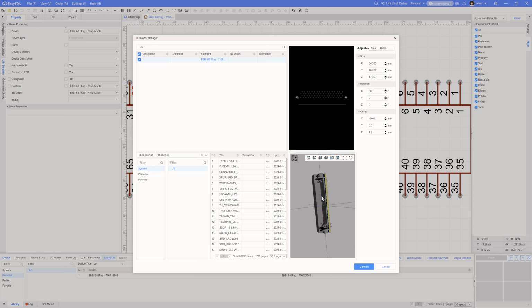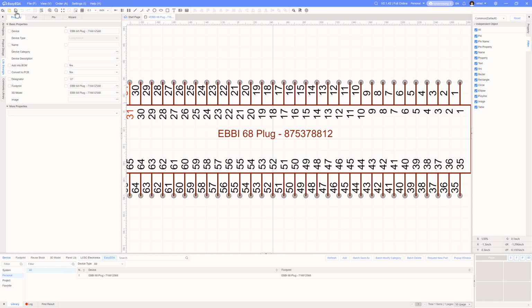It's called the plug, and I think that's looking pretty decent. Those pins seem to be nice and centered, and these other holes look good. So that maybe indicates that 3D model, I didn't have to do any sizing to it, and what I did on my PCB seems to line up as far as my footprint. So I'm going to confirm all that and see what I have left here. So I think I have a device.